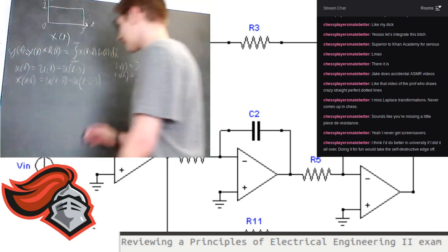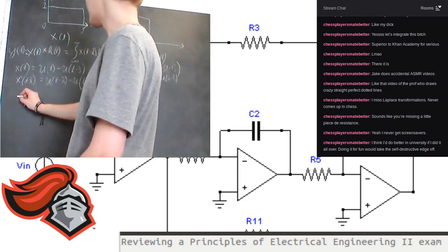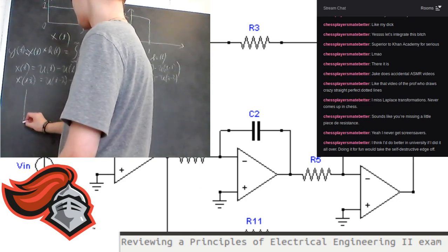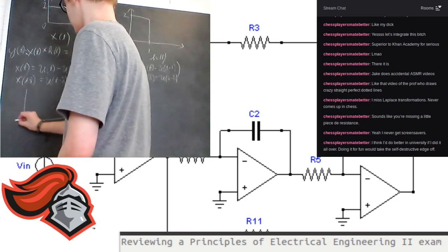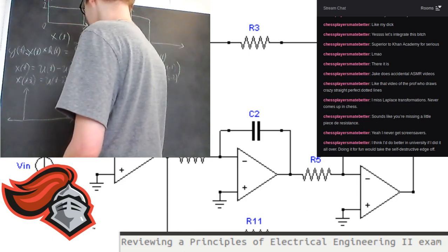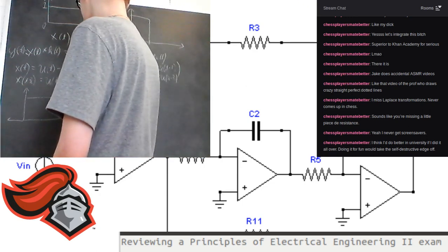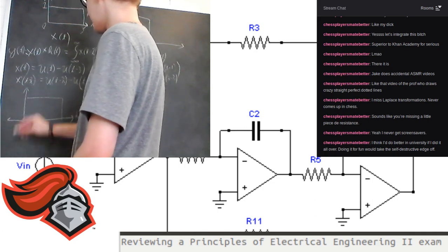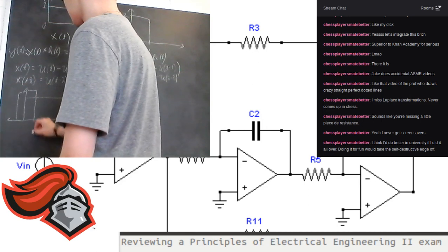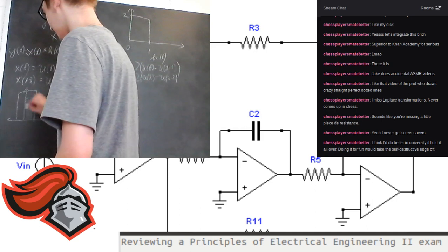What was I saying? Oh. So basically what the convolution is doing is, let's just say you layered the graphs on top of each other with respect to lambda. Here's our x(t). Here is our h. And then this intersection is what we're finding the area of in the convolution.